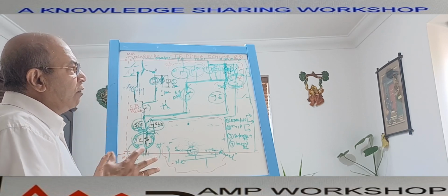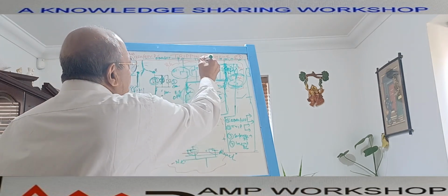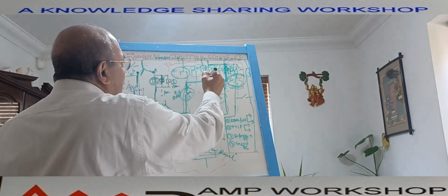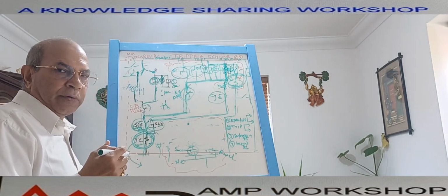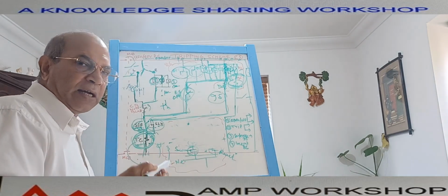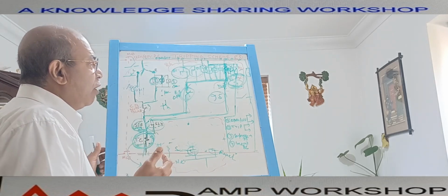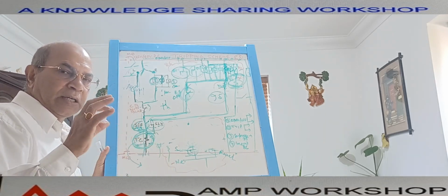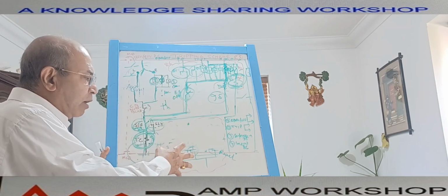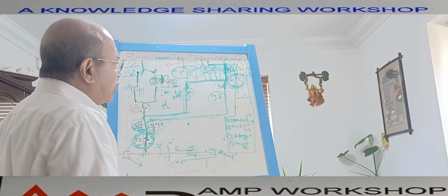In the digital relay, another option is there. In this tripping part, we can add the digital relay direct output. Yes, the direct output we can use in the lockout relay also, if the digital relay is configured in that way. But we always use the digital relay output contact in the lockout relay, and then the lockout relay will get tripping. So these are the various parts of the tripping scheme.